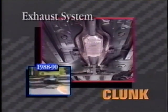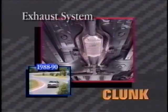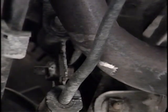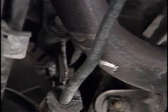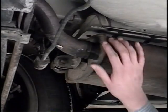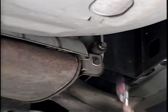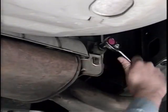The exhaust system is a possible source of some underbody noises. Metallic clunk or thud noise during normal movement on some 1988 to 90 cars may be caused by a loose or misaligned exhaust system contacting the rear stabilizer bar. Check for evidence of this condition by examining the exhaust pipe and stabilizer bar for marks caused by contact, and realign the exhaust system as necessary to provide sufficient clearance.